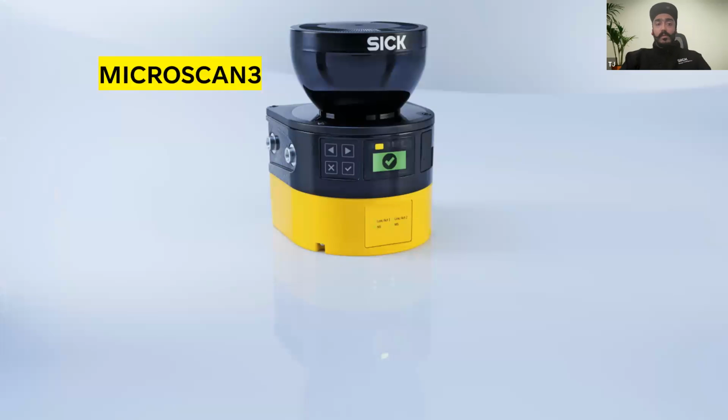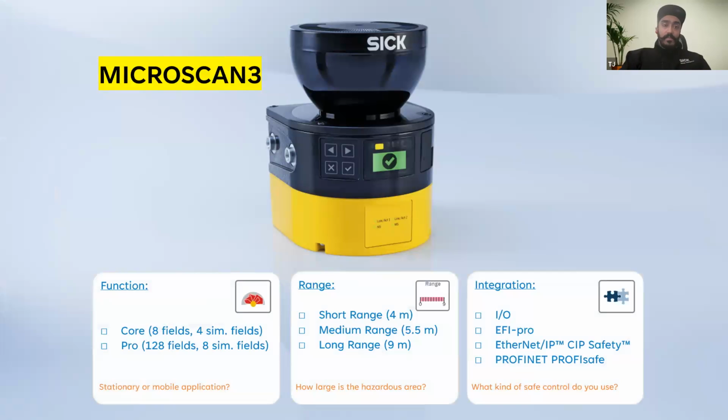And real quick, talking about the portfolio, I'll talk about the popular ones. The first one is microScan 3. Essentially, we have a lot of different variants in this, but they can be divided based on the range, which is we have a 4-meter variant, which means you can look up as far as 4 meters for your protective fields. Then we have a 5.5-meter variant, and the longest range that we have is 9 meters. And in terms of integration, we offer basic IO capabilities. We also have EFI-pro along with EtherNet/IP with CIP Safety protocols, and we have PROFINET for PROFIsafe protocols as well.